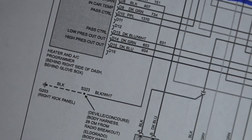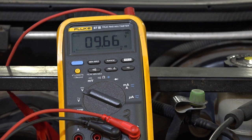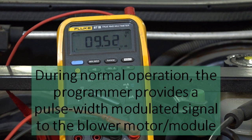There we go, heater and AC programmer. I need to determine whether it is being commanded up and down by the programmer or whether the blower motor control module itself is simply pulsing the blower motor. So I've got a DVOM plugged in to the gray wire, the blower speed control wire, and I'm looking at voltage. I believe that signal is pulse width modulated, or it might even be frequency modulated. I don't know for sure on this old beast.